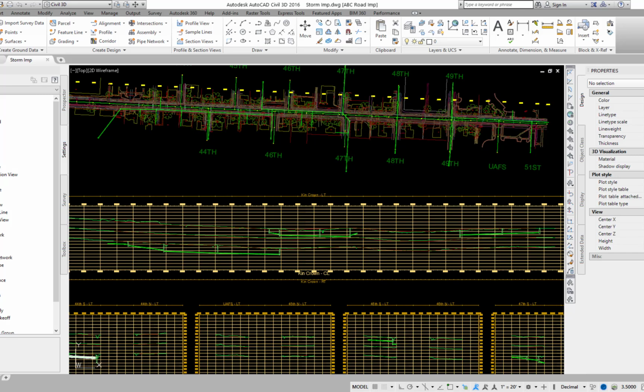If the computed full flow hydraulic grade line for the outlet pipe at the upstream structure is less than the soffit elevation, I use inlet control and critical flow for computing the hydraulic grade at that location. If the hydraulic gradient in the structure is less than the soffit elevation of the inlet pipe, I use the soffit elevation as a hydraulic gradient for the upstream calculations in the pipe.